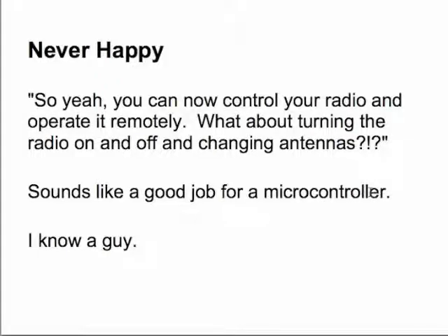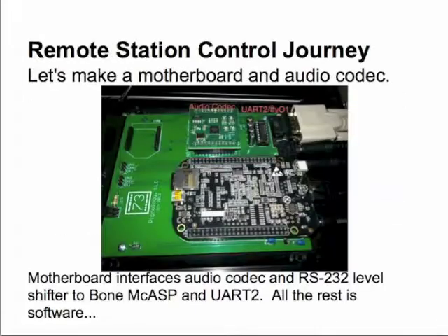So I'll jump into what he did at Hamvention. I actually handed this off to him, and he presented a couple slides. What he created was something called a station controller. So using this interface right here, this XB, we have a wireless link. An XB is a digital data radio that can create a mesh network. There's one in Pig Remote, and one in the station controller from Sierra Radio Systems. Then I wrote software on the BeagleBone which will take in a network stream, send it to the XB, which sends it wirelessly over to the station controller, and then the microcontroller in the station controller acts upon it.